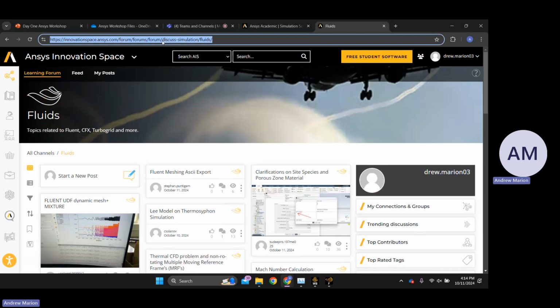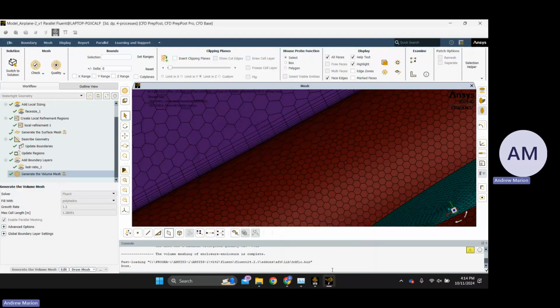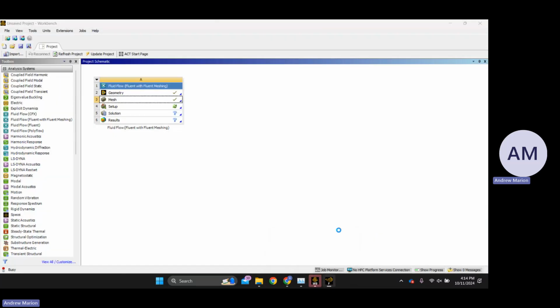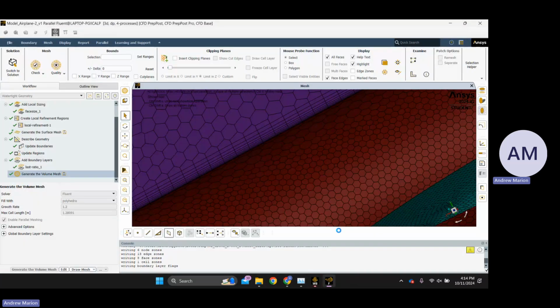2.1 million. I was like, oh wait, no, the cells are determined by it. I thought you were asking how fast it generates. He's saying he got more cells because of the cores. You had 2.1 million cells? That means you put a setting in wrong somewhere. You put something in that's way smaller than normal.